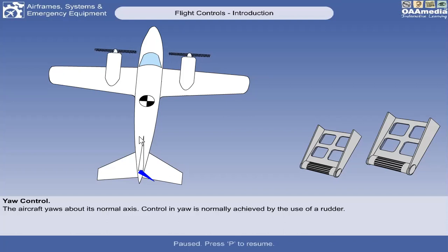When you're on the ground and you step on the left and right rudder pedals at the same time, that is where the braking system of our wheels will engage. But if it's just one pedal, actually you cannot use that while in flight. You can only use it once the aircraft is on the ground, so that's the only time it becomes operative. But in regards to the movement of the rudder, it can be either you're pushing the left rudder pedal forward or the right rudder pedal forward.